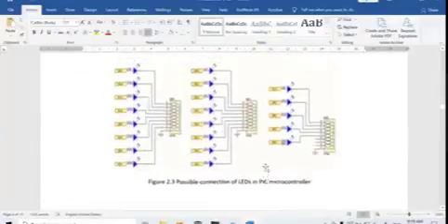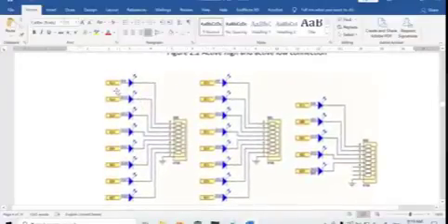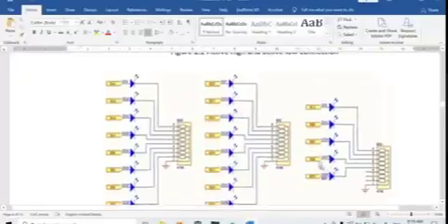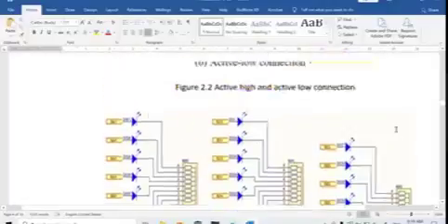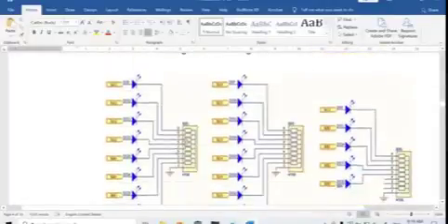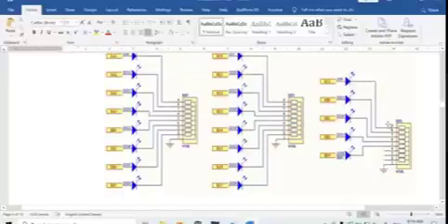And this is some possible connection. So basically, you can connect multiple LEDs to the microcontroller. For this case, you can see we can start from RA1, RD0 until the last one, RA2. Okay, this one is not related. This one is for the encoder. This resistor will be represented by the resistor pack shown here. Okay, so you can see the configuration here is still active high. Why? Because giving a high signal will turn on the LED, because it is going to ground.